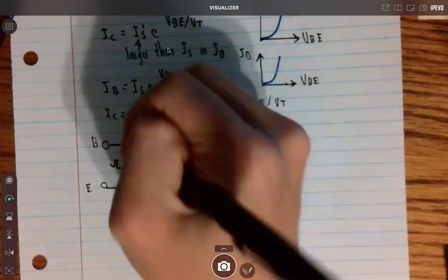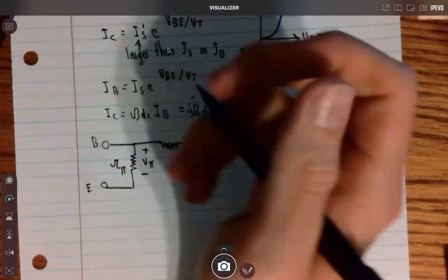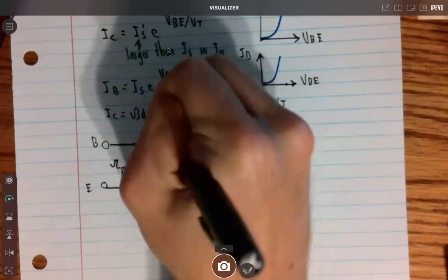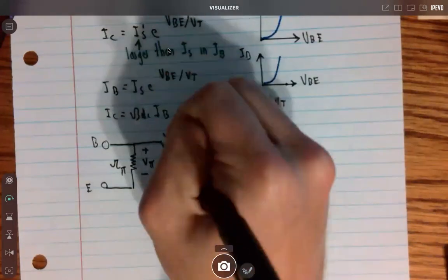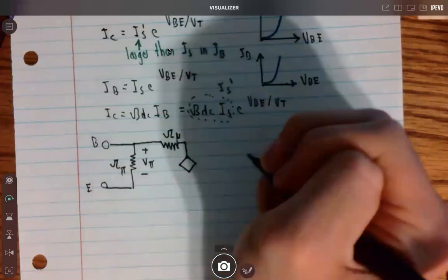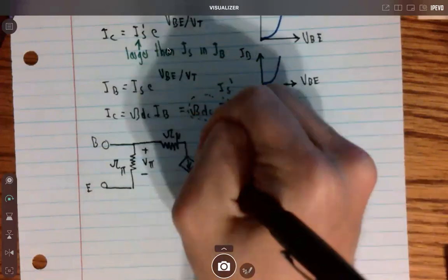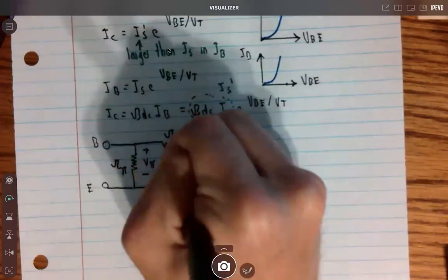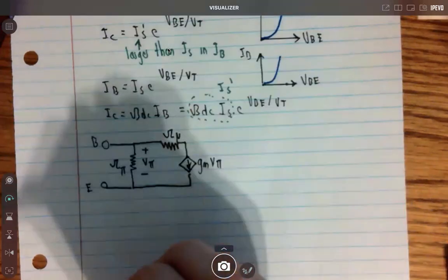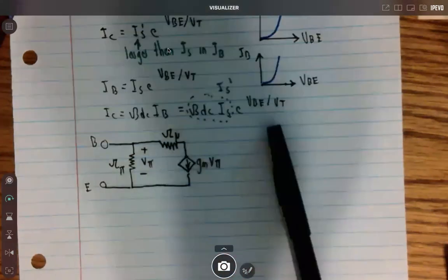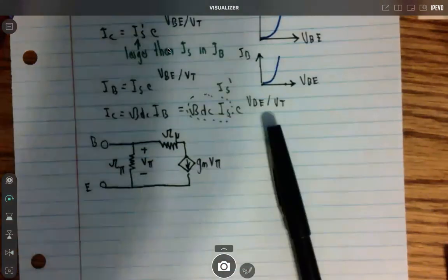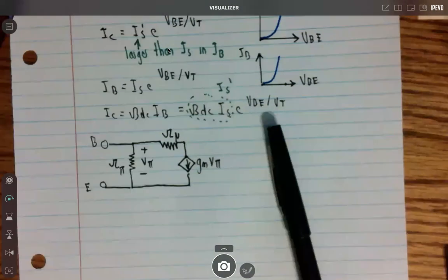And then we have a link resistance between the two. The link resistance has very high resistance, and so most of the times we don't even take it into account. So I won't even take it into account for anything in this calculation since it's so large. Then we have a dependent current source, which is gm v pi. And that just tells us the size of basically the collector current for the input voltage we have. And then we're going to have the output resistance here.